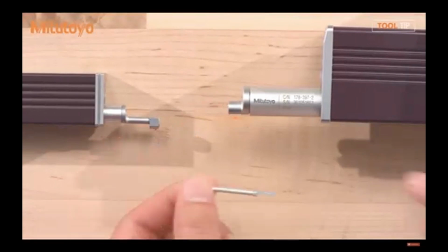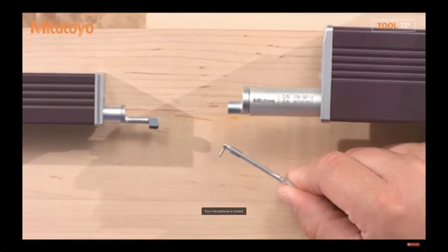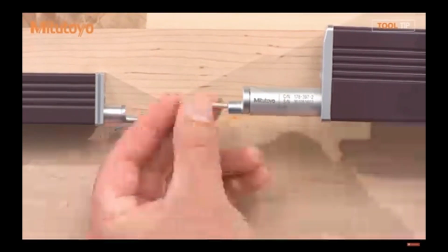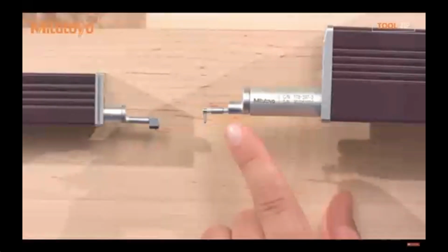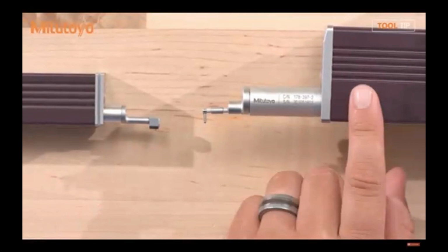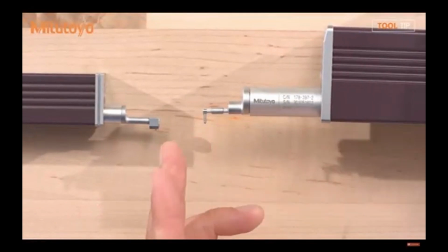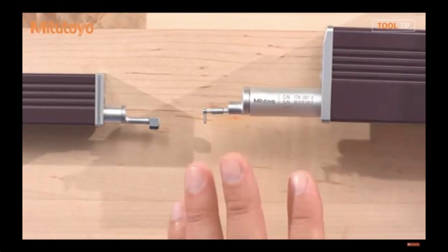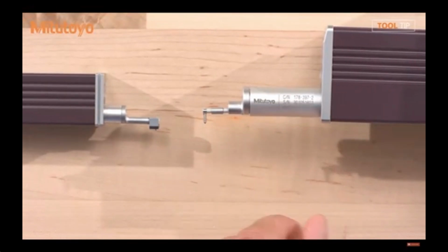You have a stylus, and the stylus is the piece that contacts the surface to do the measurement. The stylus feeds into a detector. The detector takes the movement, translates it into a signal that can be measured, and then we have the drive unit, which pulls the stylus and detector assembly back and forth for the measurement. That'll plug into an amplifier, which is where you get your readings from.